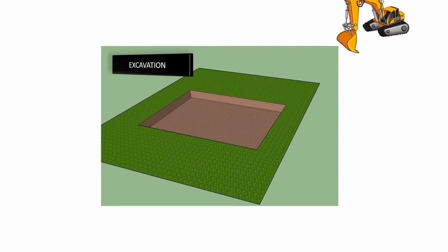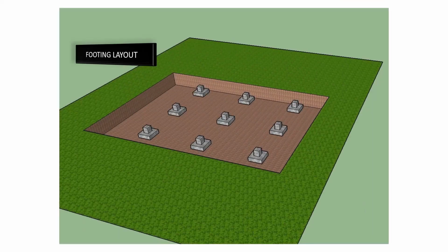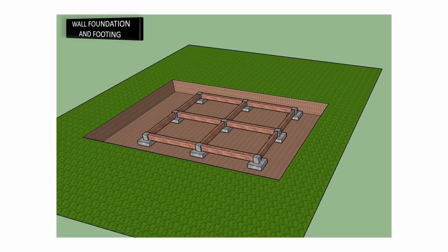Firstly, there will be an excavation carried out, and there will be a footing layout plan, and on top of it there will be a wall foundation. We should keep in mind that the plinth beam will be resting on the wall foundation. So knowing that, we can reduce significantly the amount of reinforcement in the plinth beam.